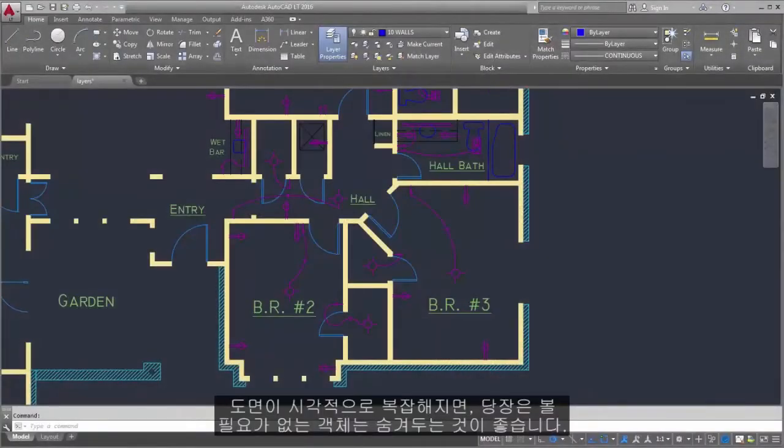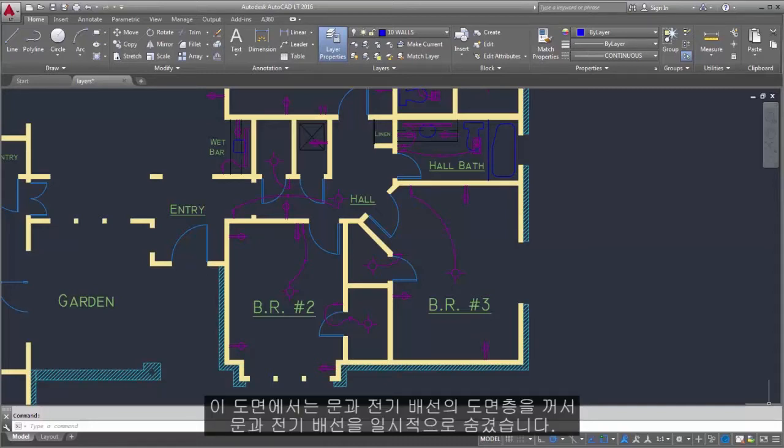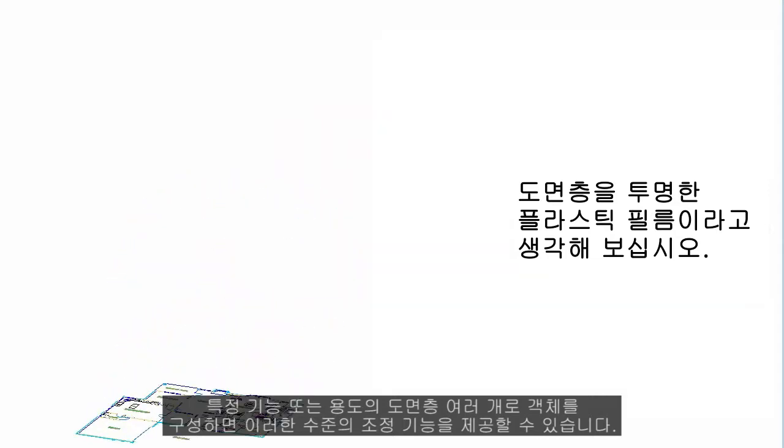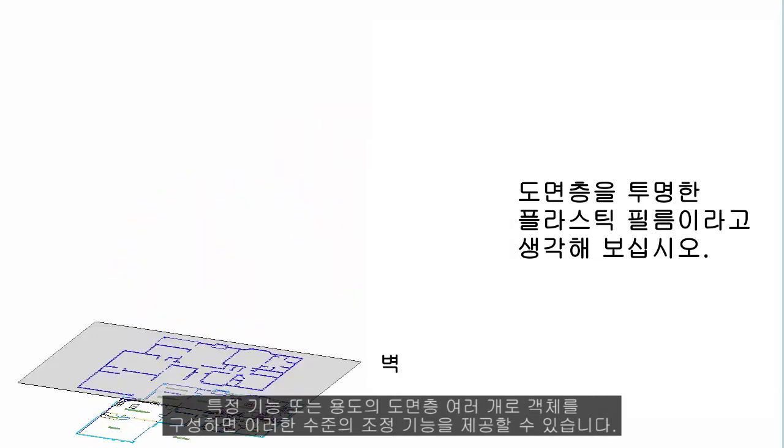When a drawing becomes visually complex, you can hide the objects that you currently do not need to see. In this drawing, the doors and electrical wiring were temporarily hidden by turning off their layers. You can gain this level of control by organizing the objects in your drawing on layers that are associated with a specific function or a purpose.